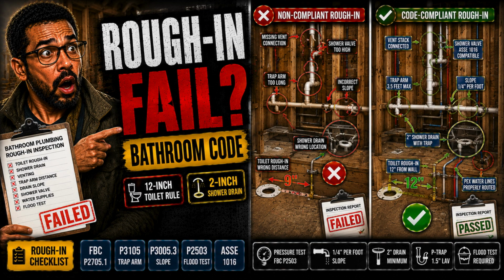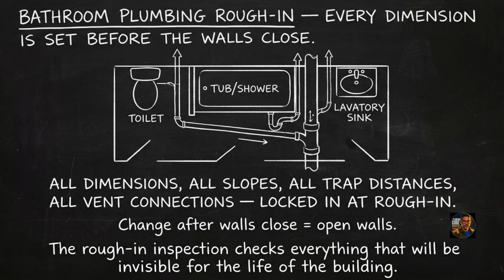The most important plumbing inspection in a bathroom has nothing to do with what you can see when it is finished. It happens before tile is set, before fixtures are installed, before any wall is closed. It is the rough-in inspection, and every dimension, every slope, every trap arm distance, and every vent connection is locked in at this stage. Change any of it after the walls close, and you are opening walls to do it.